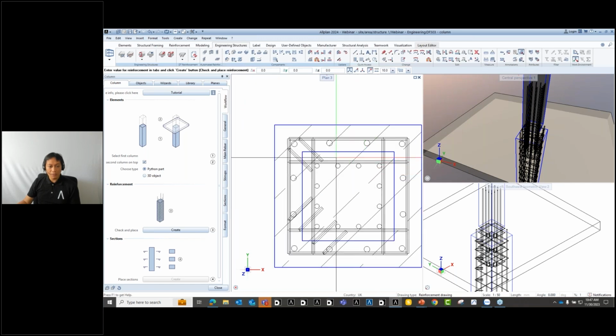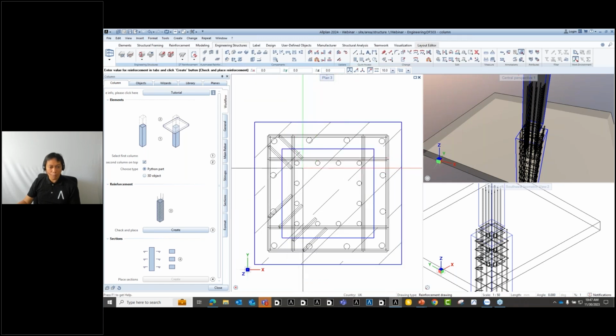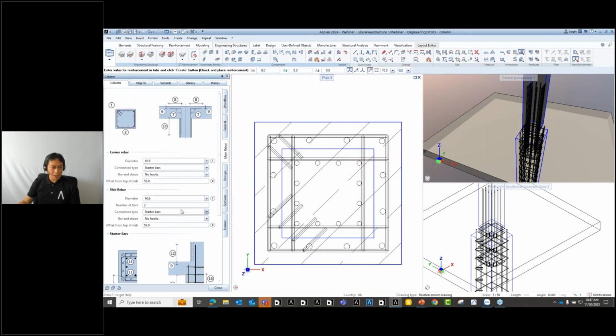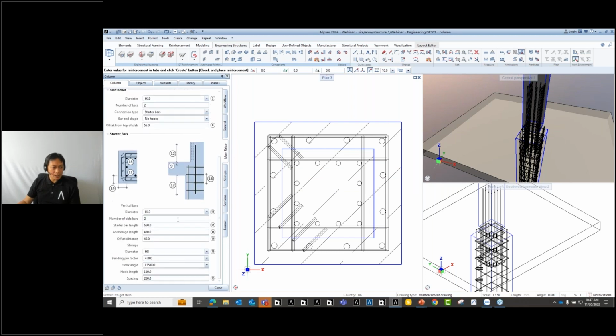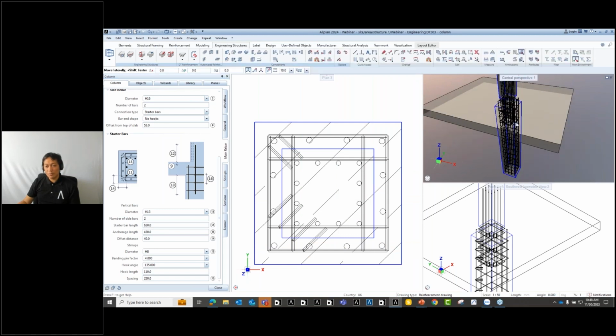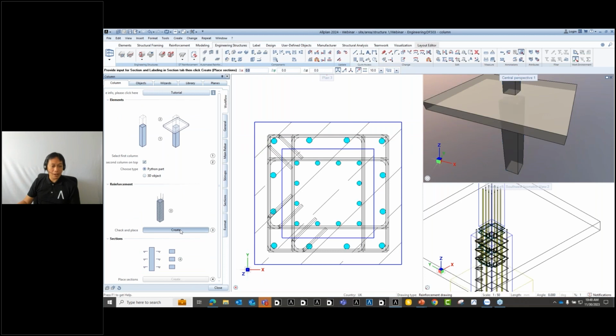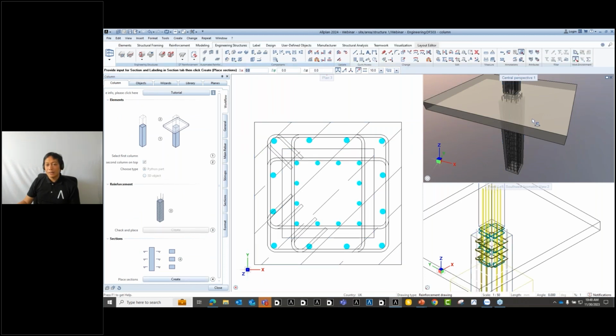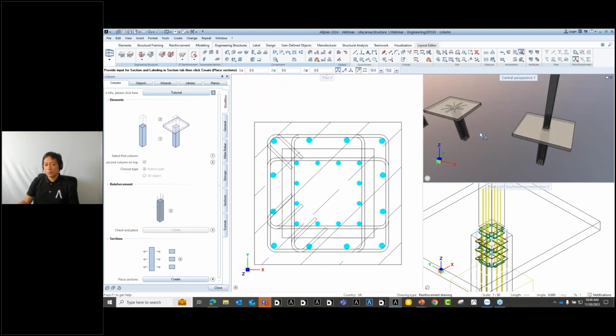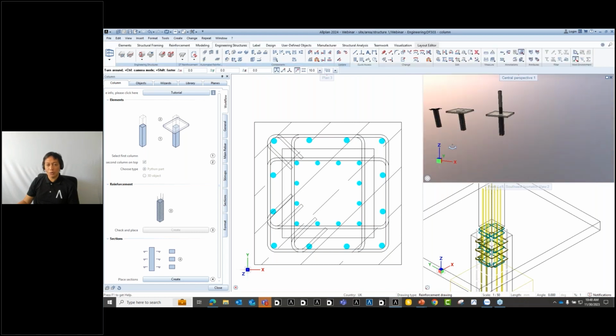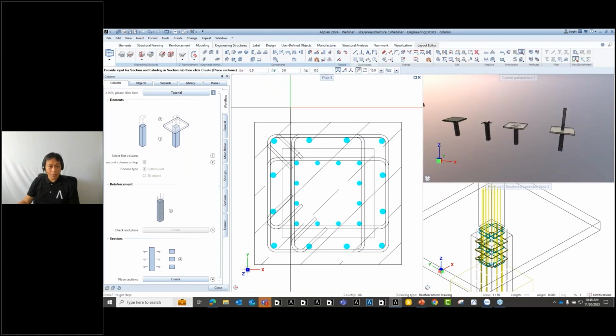And as you can see, I just changed some of the bar numbers. So that was changed from here, of course. So you have more information below. What are the lapping lengths? What is the diameter of the bars that you need to provide? And then if that is already fine with you and the correct detail, then you just go to workflow and then say create. Okay, so moving forward now, this is for the column. These are the new features of column.